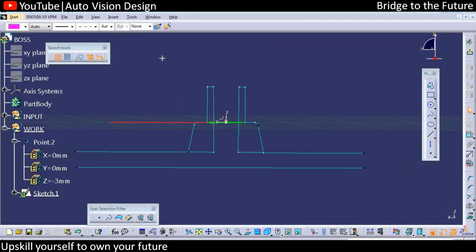Okay, so this height we can just check for that. 5 to 7 mm we are going to consider for this height, that is sufficient. Minimum 3 also we can create somewhere like here. With respect to that we can add, because whatever the maximum height, we have limitations. So with respect to this design guideline, we have limitations on maximum height also. So with respect to that we can consider how much height we have to the BIW.